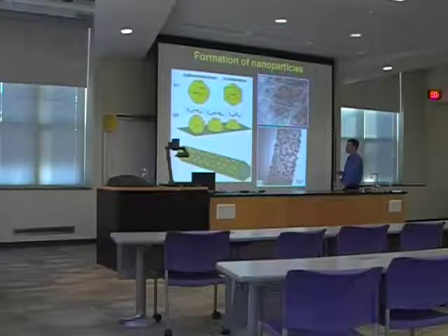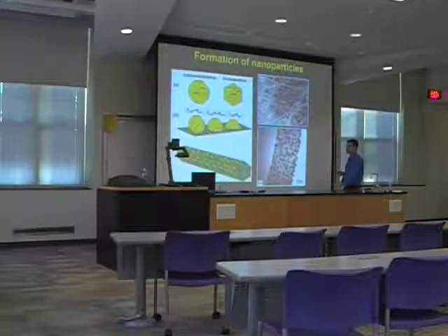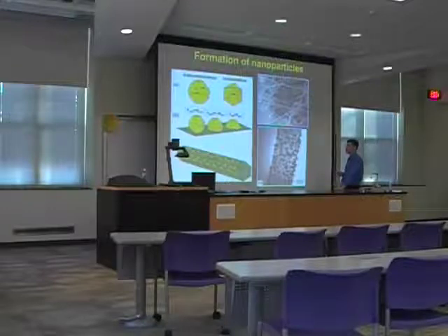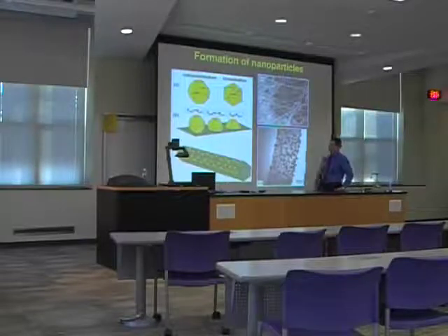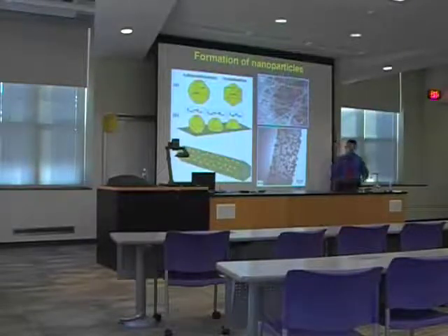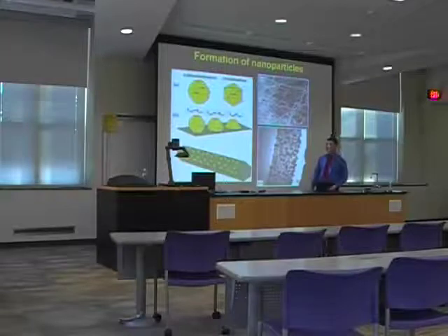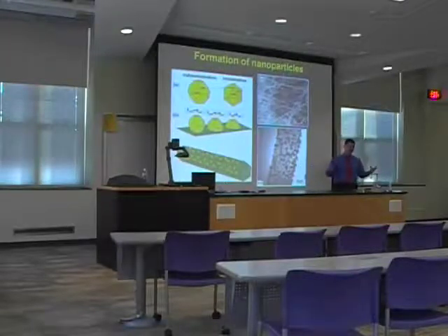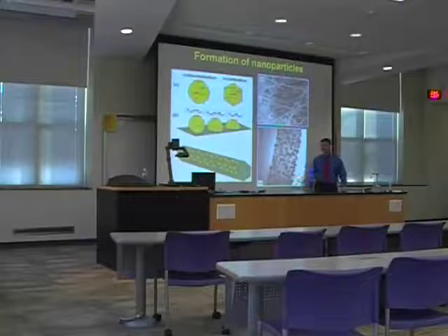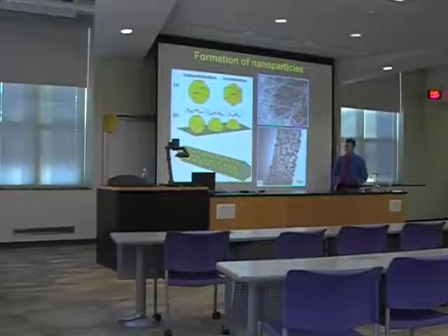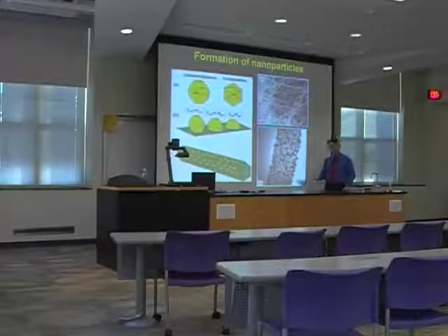So if adhesion energy is much smaller than surface energy, you will get almost complete spherical shape on the surface. If they are equal, you will get half of the sphere. And this is basically how a nanowire coated with nanoparticles looks like. Why we need those kind of nanostructures and why they're so applicable. In general, nanowires or any kind of extended nanomaterials have very high surface to volume ratio, which means that any changes in the surrounding environment will affect electrical properties of these structures.